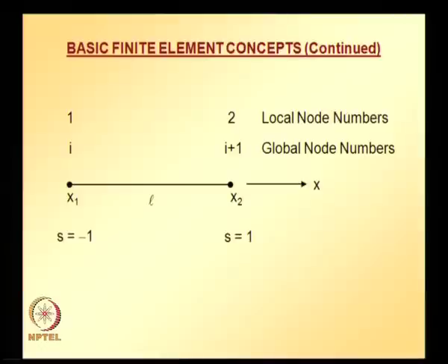and here I am going to introduce you to a new concept. Later, when we are actually assembling the stiffness matrix or the force vector, we will be using a numerical integration scheme. At this stage, we will be using Gaussian quadrature, and the integration becomes simpler if your element ranges from -1 to 1.